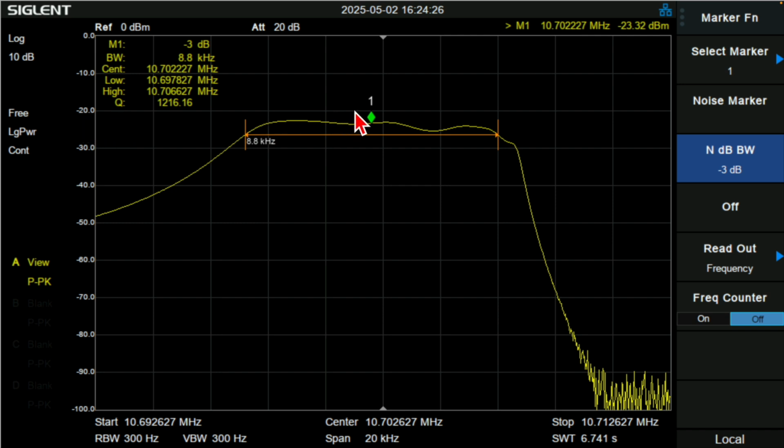It's not that I've suddenly got an extra 20 dB of loss, which would not be good. But it is measuring, if you take 20 off that, a slight bit more insertion loss than the NanoVNA did, but not a great deal.